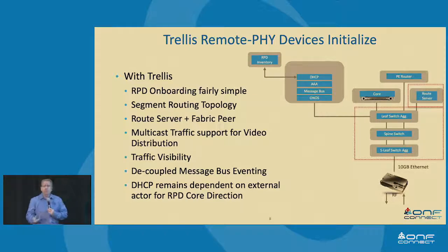Multicast traffic is a pretty big deal. In the HFC network, our video traffic was combined electrically and then delivered down in frequency allocated bands, obviously away from the data. Well, that RF portion at the final edge is still the same in remote PHY, except that remember, there's now a 10 gigabit Ethernet optic going down to the device. So the delivery of the video in broadcast terms is a multicast, right? So Trellis will get that down to us as well as our DOCSIS data.